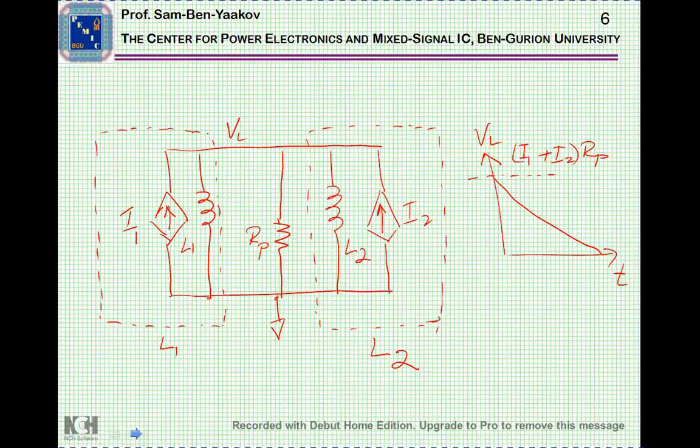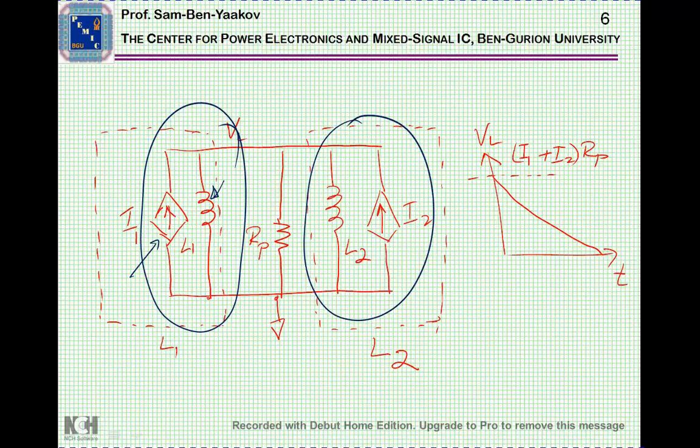So here is the problem we have. We have one inductor, which is now represented as an inductor without current plus a current source. We have another inductor represented the same way. If the currents are not equal, there is a difference. This difference should go somewhere. Well, in reality, it'll go to some parasitic resistance that exists, as high as it might be, but there's some resistance, and the difference will actually flow through this resistor.